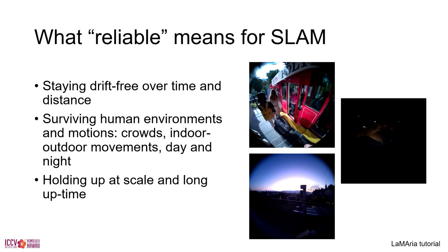Another one is to make all of the modern systems work robustly. They're all VIO systems, so visual inertial odometry. They combine visual signals and inertial signals to together estimate the motion. And that works great. Those two signals are highly complementary. The inertial sensors are really, really good at very short-term motion estimation, very robustly and very cheaply, energy-wise and so on.